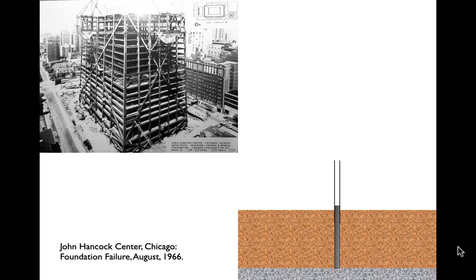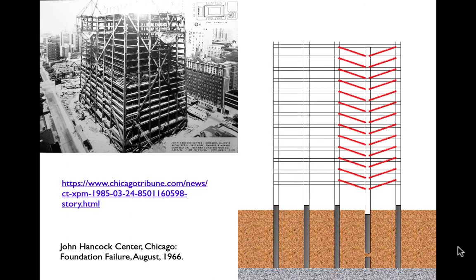And when they did that, it pulled the upper half of the caisson with it. And that split the caisson, pulled that caisson not completely out of the ground, just a few inches. And the soil then rushed in. It was able to sustain the load of the first couple of floors, but eventually not when the structure got to 7 or 8 stories.